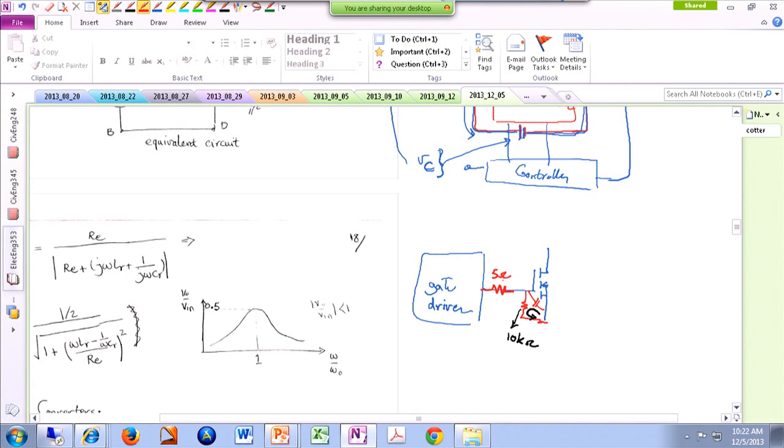Okay, you're just putting the resistor in series with your cap, so that you're limiting the current, because ultimately the current that appears over here is the current that you're drawing from your source. And if your source is not capable of handling impulses of current, then it may create some noise somewhere else that is going to bother the system. So you add a little bit of resistance over here to cut out the peak value of this current. Other than that, it doesn't have any functionality.